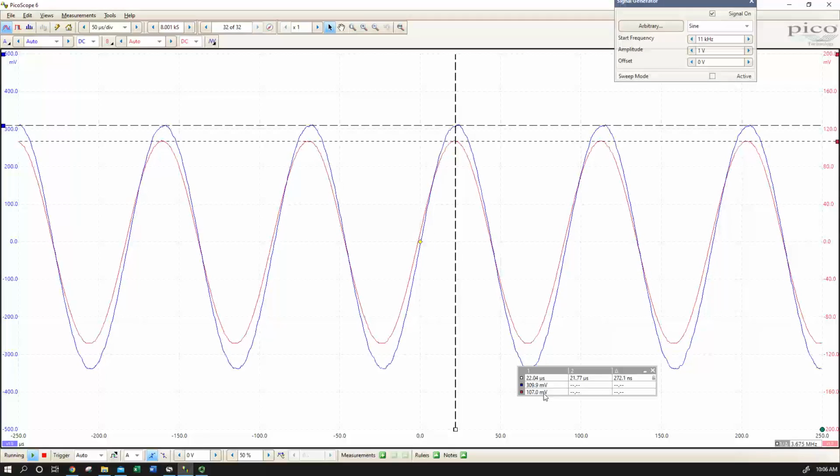Why isn't it 100%? Well, we do have our output impedance of our AWG, and we do have at least a 50 ohm resistor, real resistance associated with our 0.1 Henry inductor. So that's 50% of what we have of our deliberately added 100 ohm resistance. But the output impedance of our AWG is contributing something that is not accountable necessarily in our calculations.